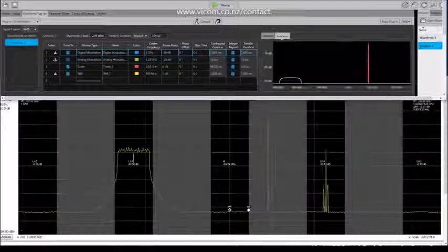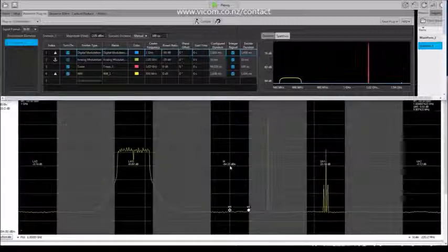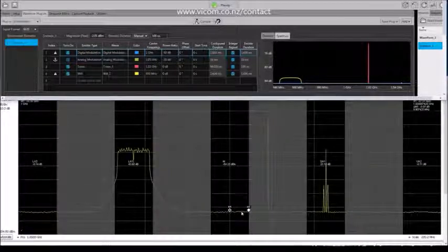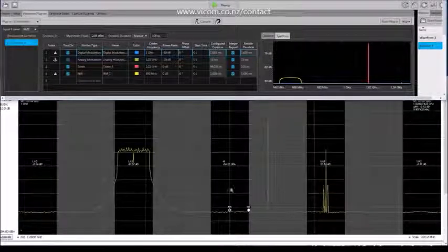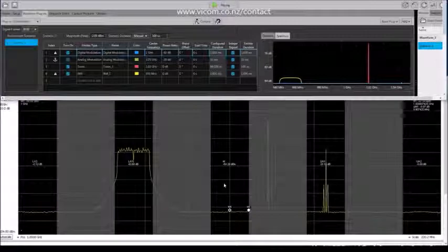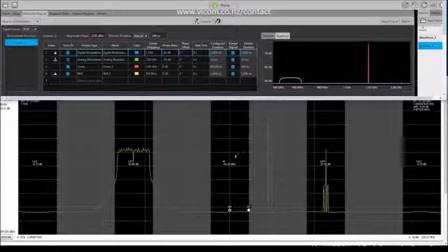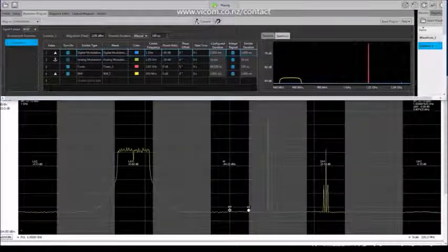And we can see that looking at the spectrum, we have this particular spectrum. And we have one in here that's very low. It's in the minus 60 dB range. And we really can't see it on the spectrum analyzer at this time. So right now we're just outputting this one signal out of one channel of the AWG. So what we can do is